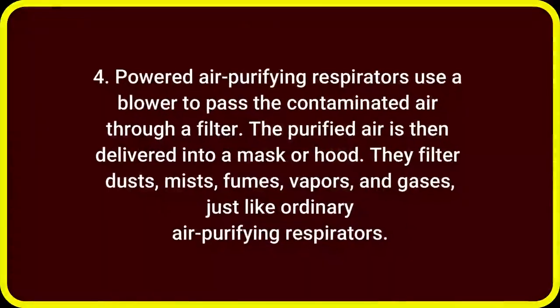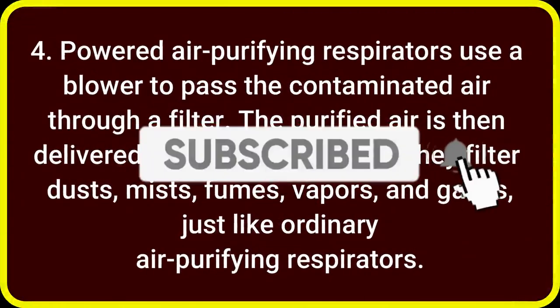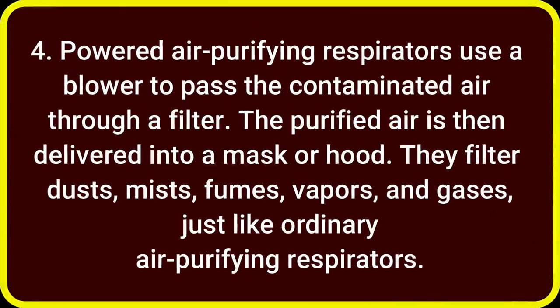Number 4, powered air purifying respirators. Powered air purifying respirators use a blower to pass the contaminated air through a filter. The purified air is then delivered into a mask or hood. The filter removes dusts, mists, fumes, vapors, and gases, just like ordinary air purifying respirators.